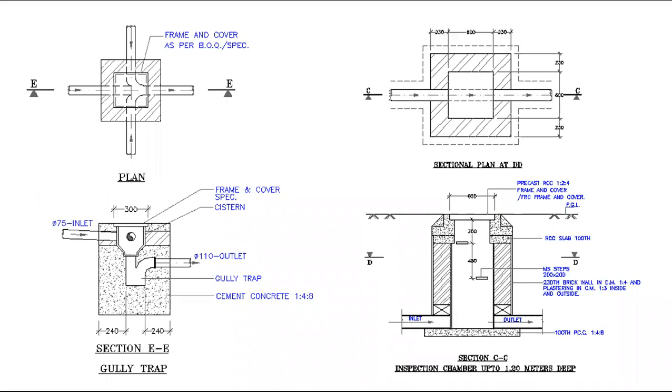You have to keep 300 mm above the pipe, 300 mm from the top of the pipe. Then only our pipe will get some cushion. Otherwise, maybe it will get damaged because of some animal or some small people will play something. Okay, sir. Thank you.